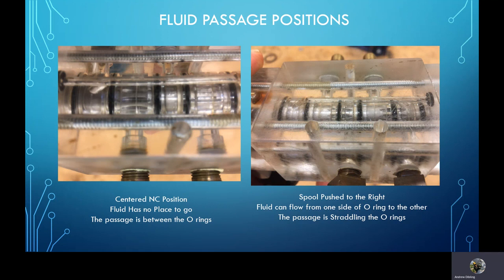And remember that all of the devices that you add to a hydraulic system will actually add some parasitic load, and therefore add to the pressure required from the pump in order to do the work that is required by the circuit. So there is some cost in doing business.